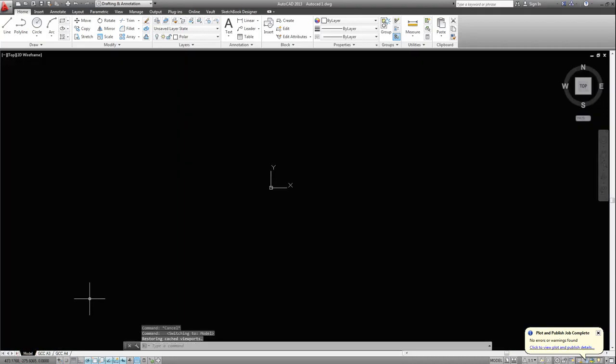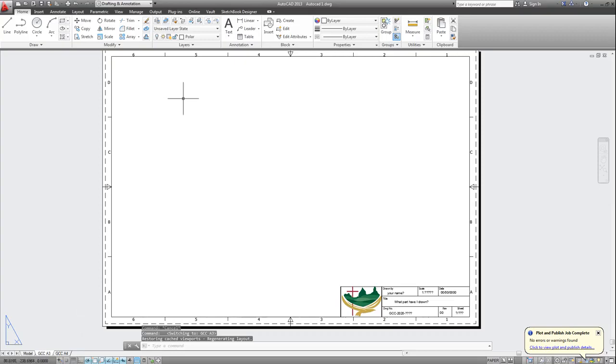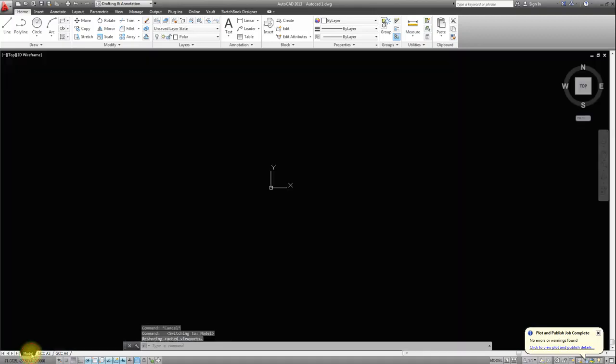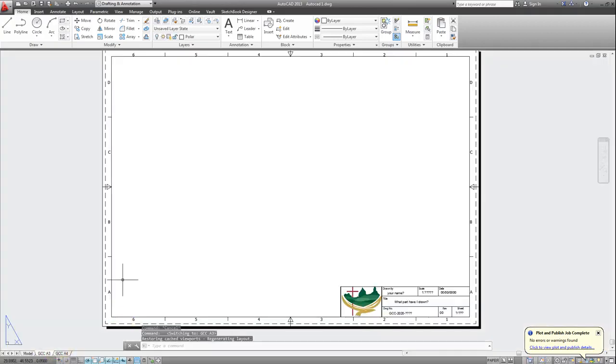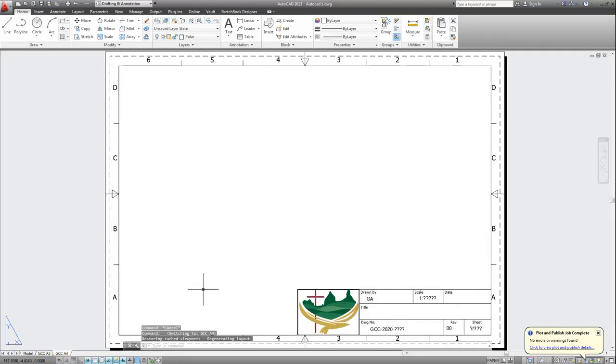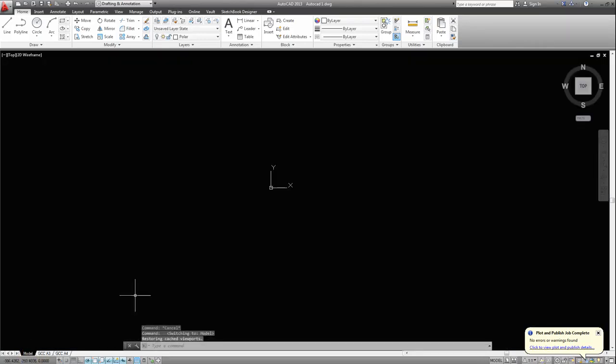Go back into model space where we create geometry. Back in the old days before CAD, all the geometry got put on a piece of paper. Nowadays it's not. All your geometry is drawn full size. I talked in the previous tutorial about how you used to scale down the size of things so it would fit on the sheet of paper. You can imagine your scale would be different on an A3 sheet than an A4 sheet if you were drawing the same size physical object. Whereas in AutoCAD we draw everything full size. You never have to think about scaling geometry when you draw in model space.